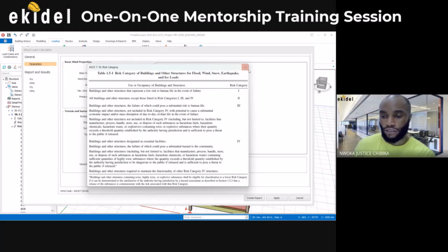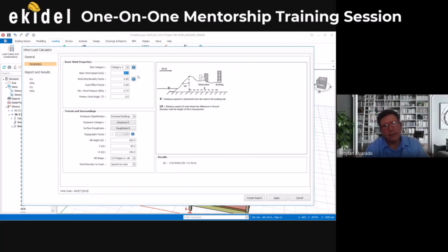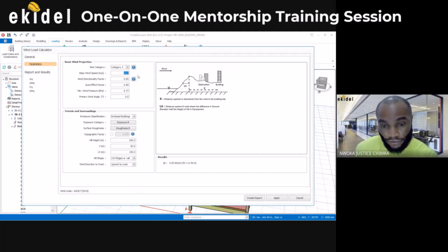So I'll cancel this, come here and choose category 3. Now, here they are asking what your wind speed is. You need to define your wind speed. I don't know, that would be like 60. Okay, 60. If you put 60 now and look here, you can see the result, which is the wind pressure, 2.6, based on the wind speed we just put.